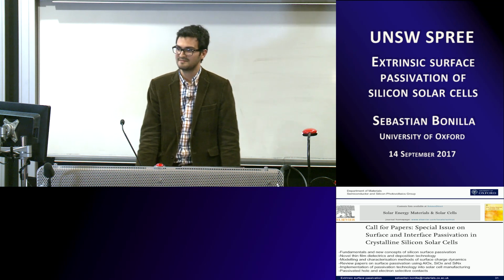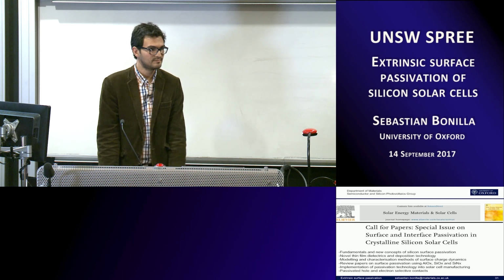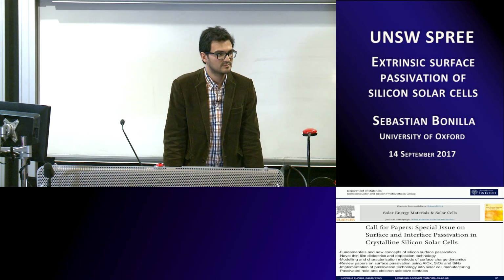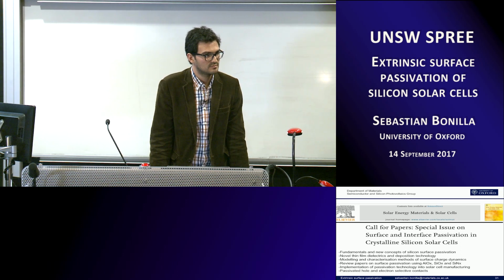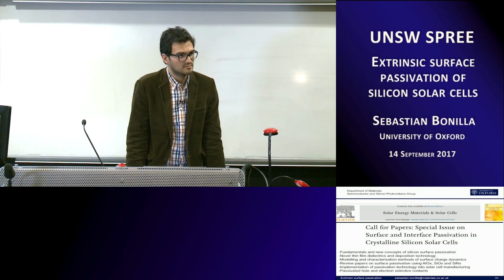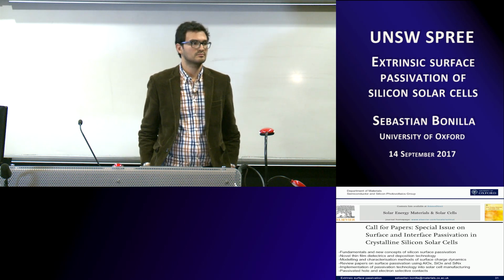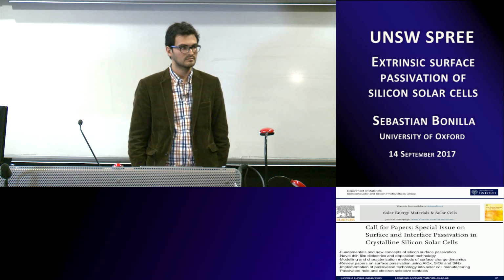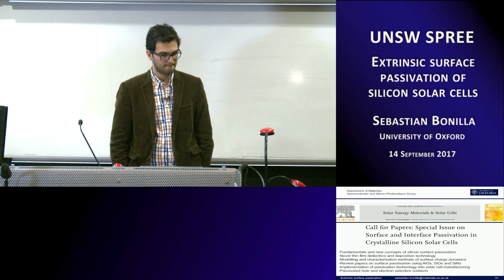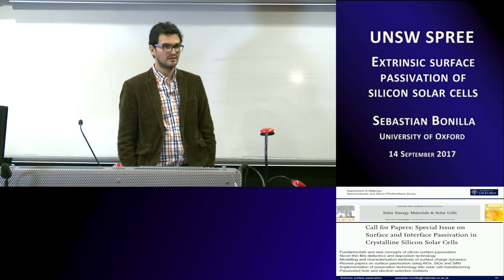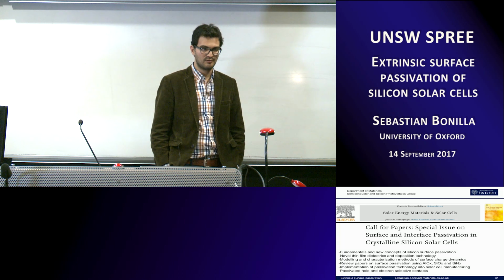Thank you. Cheers. Alison? A question about the ion charged dielectrics. Have you thought about testing them under high voltage? The reason I ask is, there have been a lot of reports looking at PID being due to sodium from the glass permeating in through the dielectric and going into the silicon. Is this something you've looked at? It's something we haven't looked at, but we are aware of it happening.